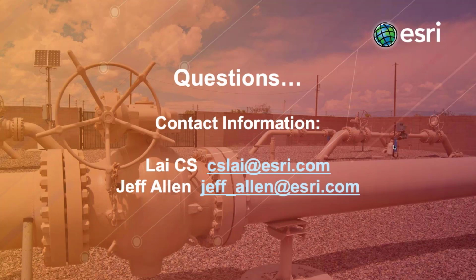Okay. Great. The next one is, when creating a point along a pipeline for linear referencing, is it considered also the terrain, elevations of pipeline underground? I think that you have covered that just now. Yeah, so really what happens is the ability to take in the concept of terrain comes down to the pipe itself, right? So the pipe itself will have X, Y, and measure, but can also have X, Y, Z and measure, right? So if I want to introduce a terrain into that model as well, I could then, and I've actually done this where I've taken a utility network pipe and draped it on the terrain and then dropped it for 2 meters of cover.